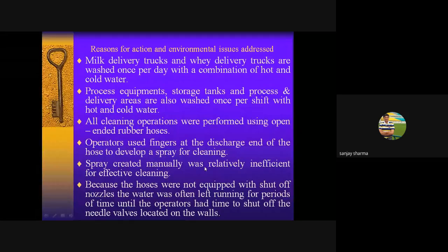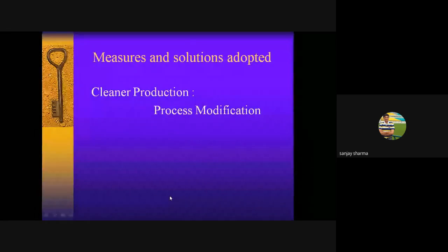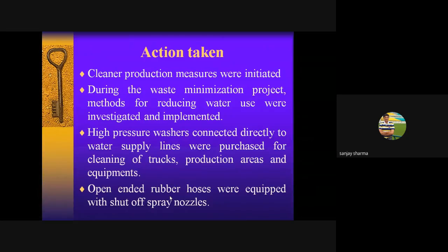The spray created manually was relatively insufficient for effective cleaning, because the hoses were not equipped with shut-off nozzles. Water was often left running for periods of time until the operators had time to shut off the needle valves located on the walls. So here also the cleaner production actions were initiated during the waste minimization project.